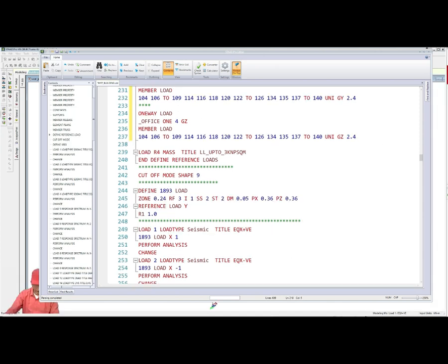And then R1 is the dead load, floor dead load, that has already been taken. Then we have to define R2. R2 is wall load. This is also dead load. 100% will be taken. Then R3 is live load more than 3 kN. The code specifies that 50% of that has to be taken for seismic load computation.